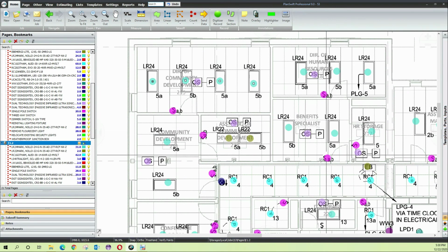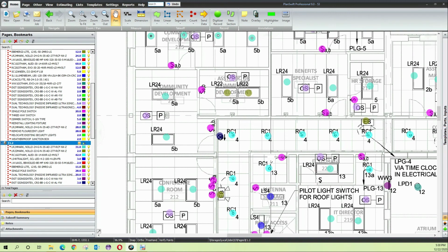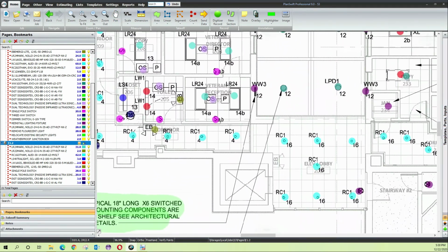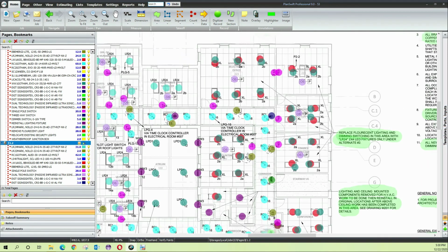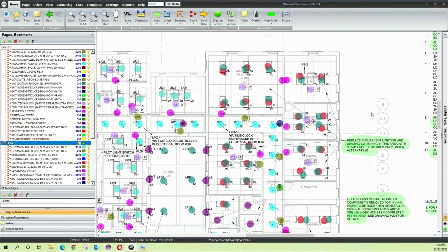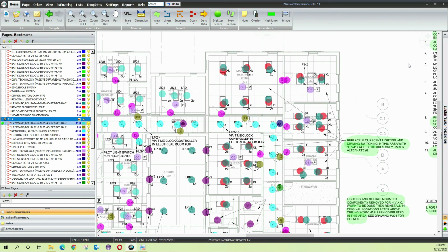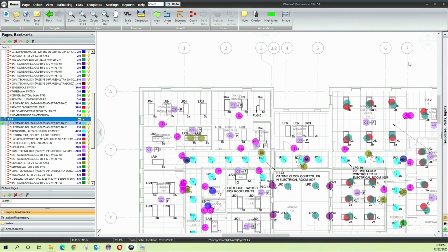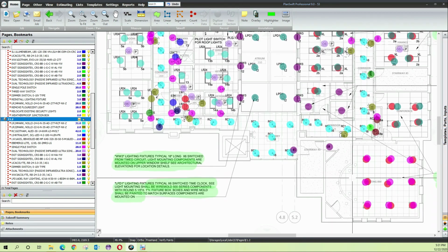So you can change the color so that it is easy to differentiate between all the fixtures. And these are bulbs: if I press on this bulb, all these dots disappear. So you can also do that in order to recheck that you have covered all the lighting fixtures and lighting control system.